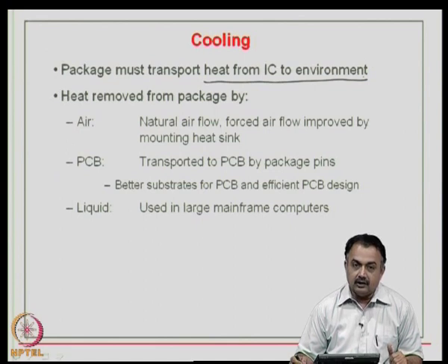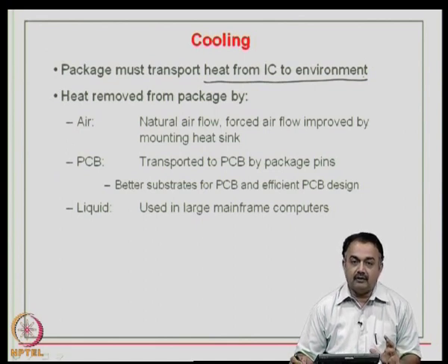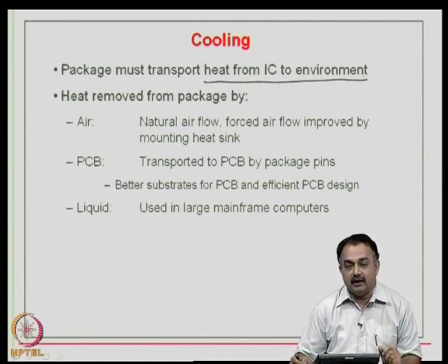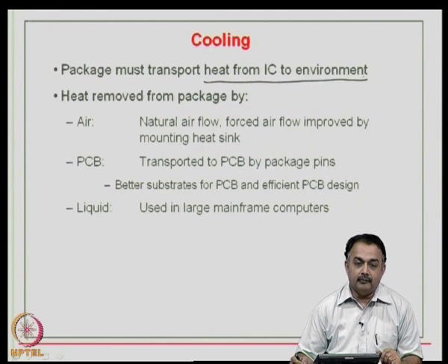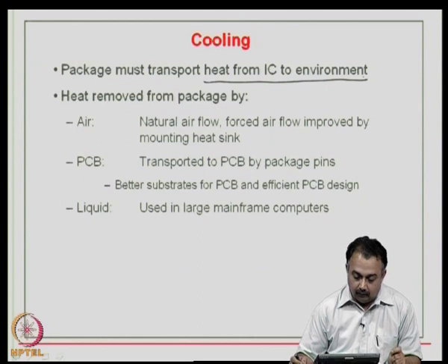So, it is a combination of silicon die, and then if you are using an organic substrate to place the silicon die, then there is going to be a problem in terms of warpage due to continuous thermal cycling at the organic substrate end also. Therefore, this heat has to be quickly removed effectively.